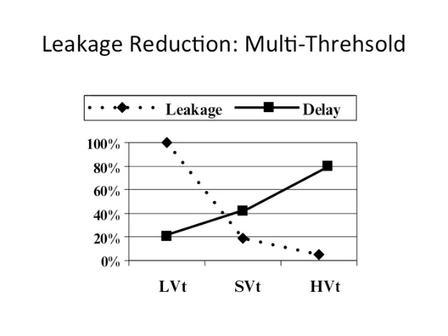So clearly in paths which are not critical you can use high threshold transistors because you can afford to slow them down, but you can then recover some amount of power there. But after that, if you want to still further reduce leakage power, then you have to trade off between delay and power. Right? You have to slow it down a little bit so that you reduce the overall leakage power. We'll also see a little later that dynamic power and leakage power, typically, are comparable. The leakage power would be about maybe half the dynamic power. So there is a good contribution from both dynamic and leakage power to the total power.